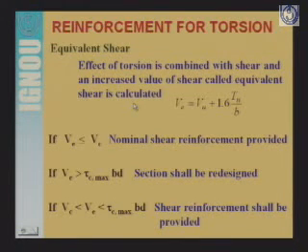We increase the value of the shear force by using a formula, and this increased value is called the equivalent shear, because shear was already coming into the member and we are adding some more.